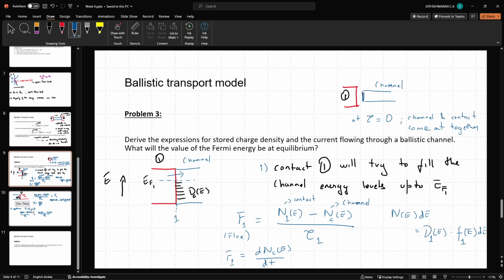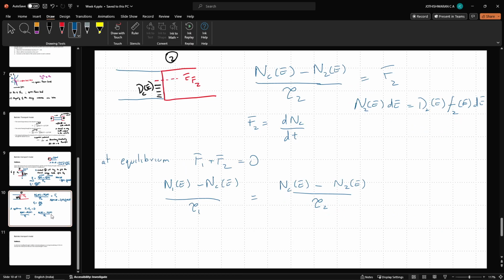The voltage is set all across the entire device, the processor or whatever higher level device that is using these transistors as its building block. So the voltages are all set up at the same time, which implies all the contact potentials and charge carrier concentrations are initialized at the same time, which implies we can assume tau 1 is equal to tau 2. That is a fair assumption to make.